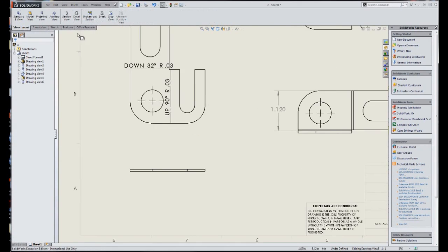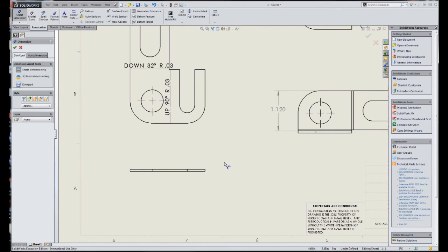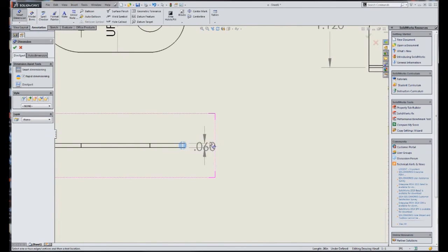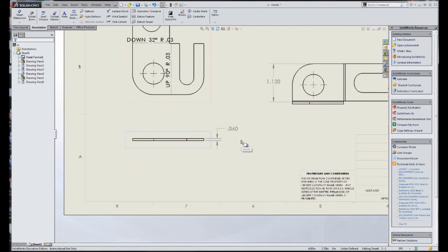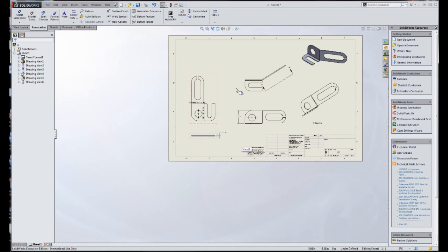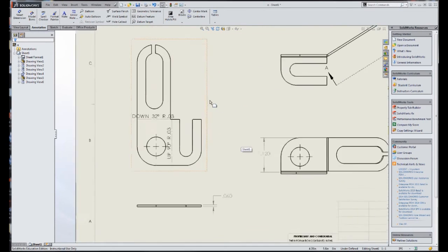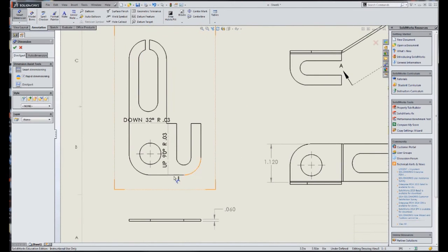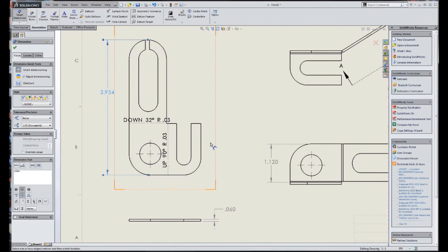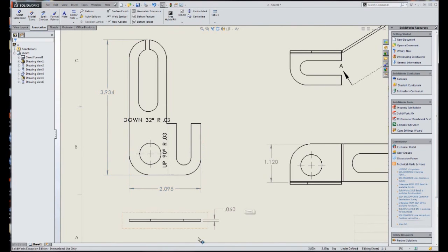Like I said, 99% of the time you always want 2 dimensions minimum, but we want to give a thickness. But the other thing is that when you present this drawing to a sheet metal person, you don't need to dimension the hell out of everything. For them to give you a good estimate, you can do the overall dimension, so the thickness, the overall length and width, and that'll help them do an estimate of what this part is going to cost material-wise.